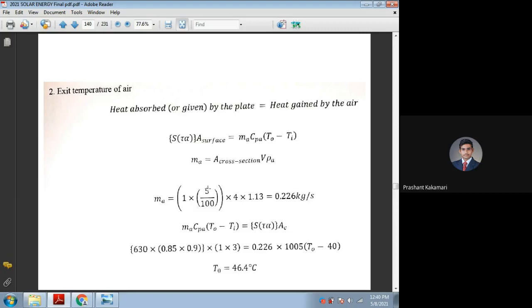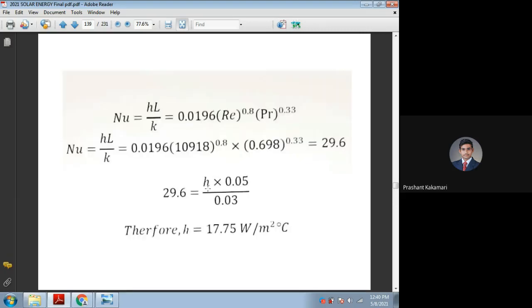And to find the mass flow rate, as I told, by the continuity equation of real fluids, area into velocity, A V, into rho, if you multiply, one can find the mass flow rate of the fluid. So again, you take the area of cross section. What is the area of cross section?